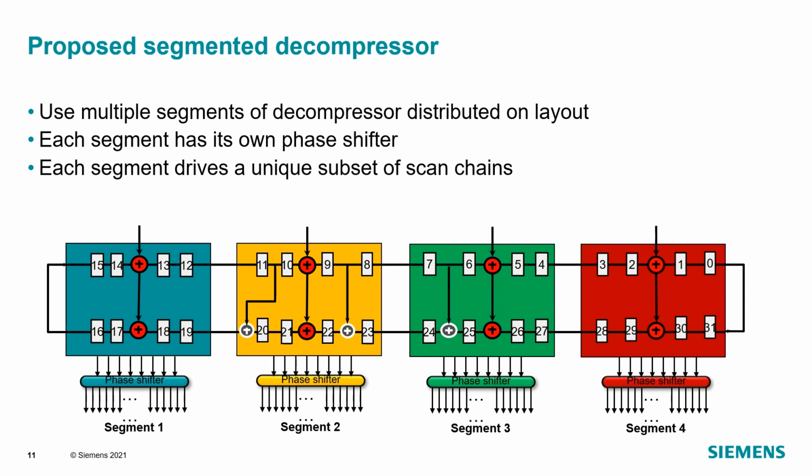So, for example, if for a given test pattern all specified positions in scan chains are driven by segment 1, the segment will be receiving an equivalent of only 2 free variables every cycle, one from its input channel and another from segment 2. So even though 4 bits are delivered to the whole decompressor every cycle, half of the bandwidth is lost to the phase shifter in segments 1 and 4. The maximum capacity available to segments 2 and 3 is a little bit better, but is still reduced to 3.